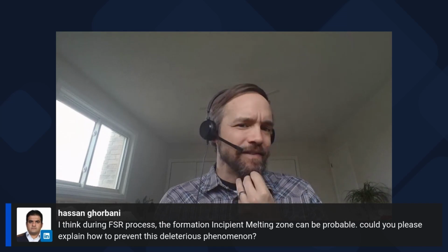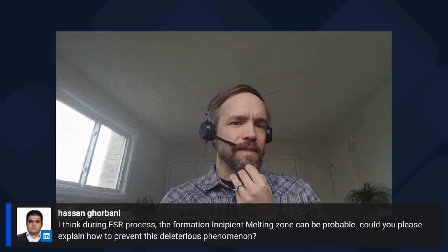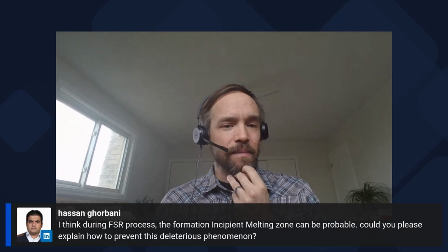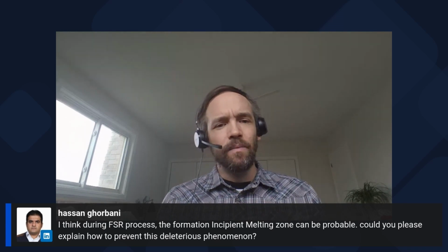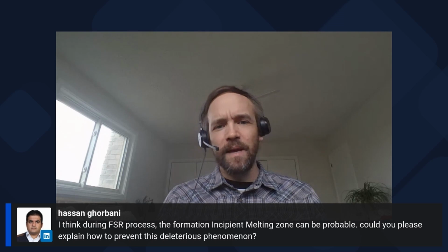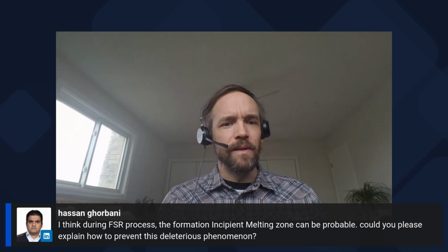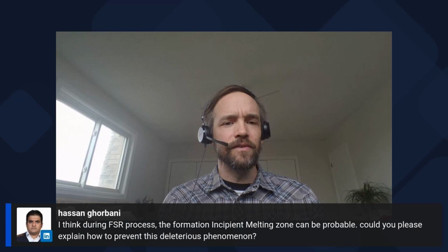I could conceive a scenario where there is an alloy where that window is too tight, or perhaps even non-existent. It might be that you can't actually fully solution something without hitting incipient melting, but so far we haven't encountered that issue. And so it's a good question. It could theoretically be a limitation for some alloys.